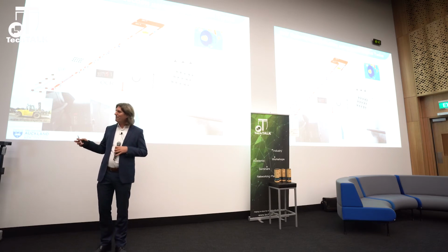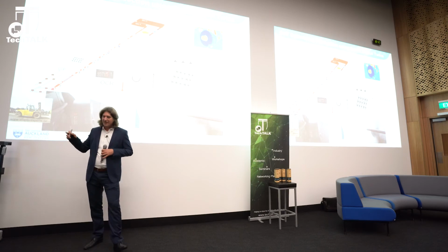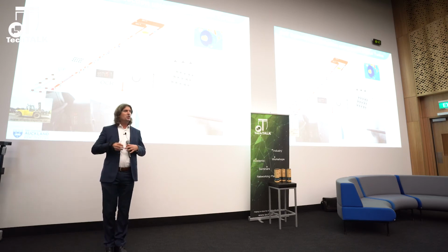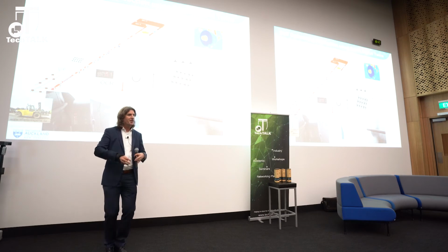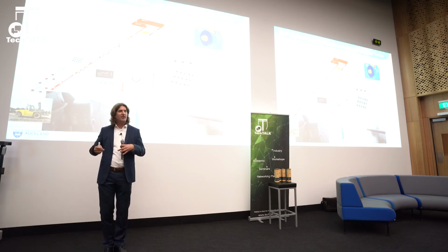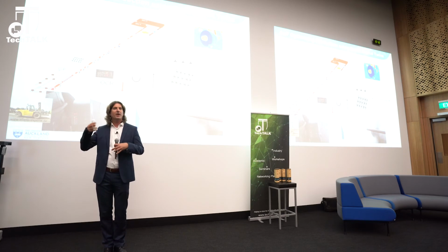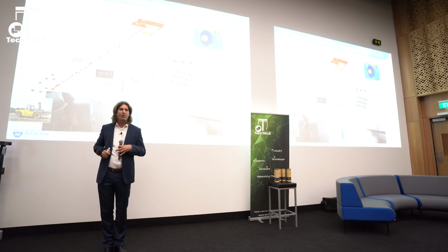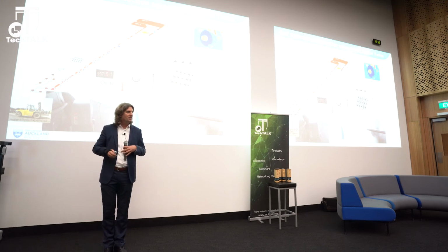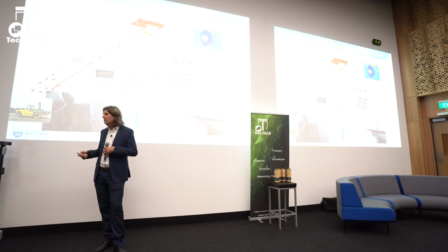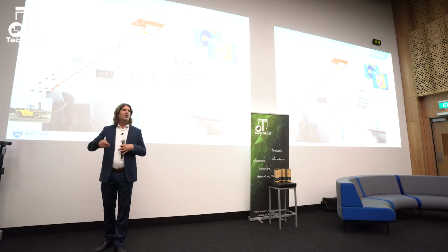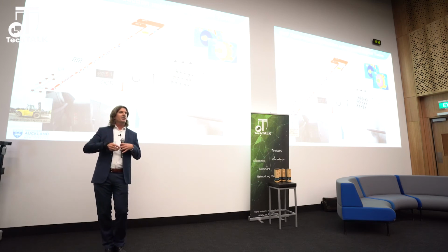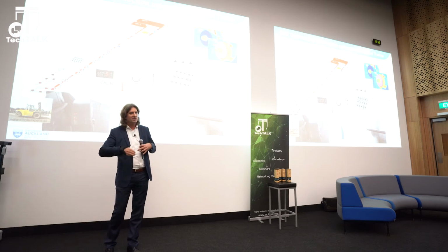So the paradigm change is that usually the machine knows best how to process that piece which is arriving. And now we have got a virtual copy of that product telling the fine-tuning to the machine. So that virtual digital twin is telling the coil shower, put me in a row where I get only 5-hour water cooling instead of the standard 8 hours. The effect is the coil arrives warm, and again, we know the temperature. And again, a cold coil would have been processed slower.